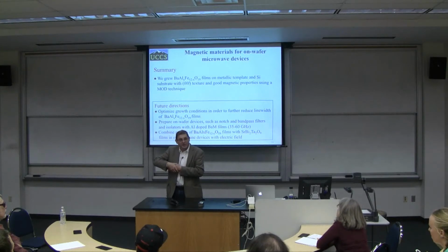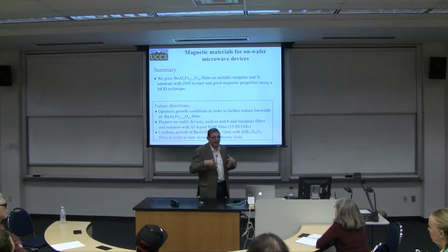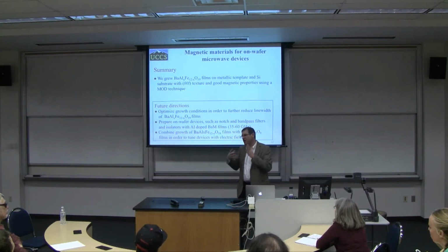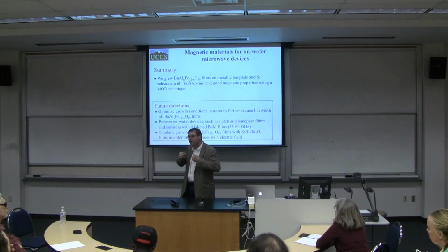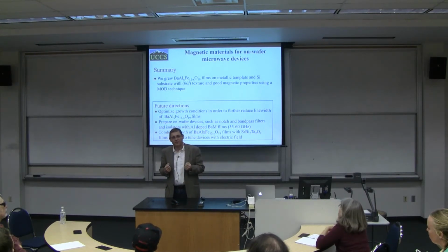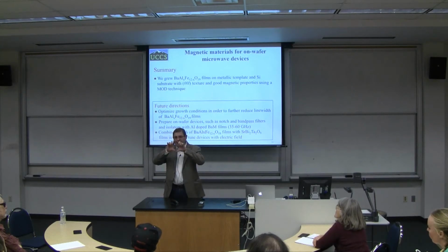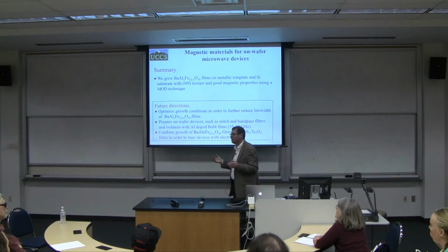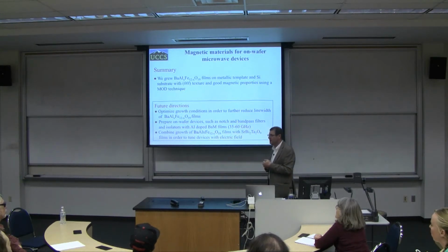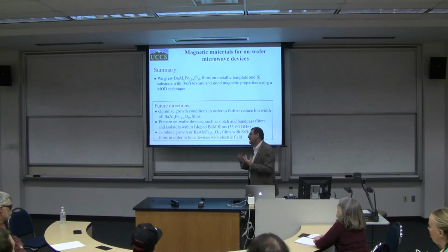Suddenly you are changing the physical dimension of your magnetic film. If you change the physical dimension, there is something called magnetostriction. You are changing the magnetic material by changing the physical size of your film. Basically, you are squeezing, for example, the C-axis, and therefore you are changing properties of your magnetic material. So this is what we would like to do.